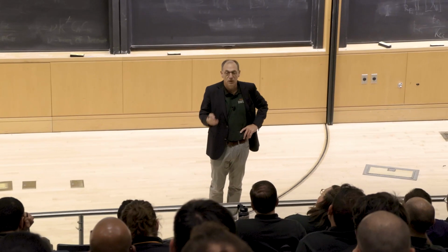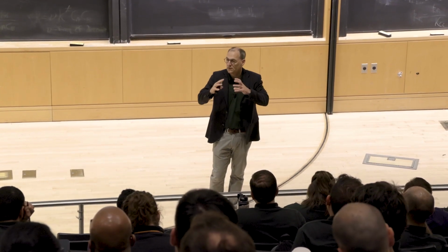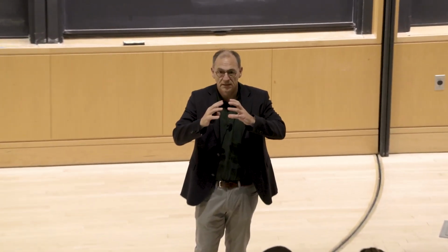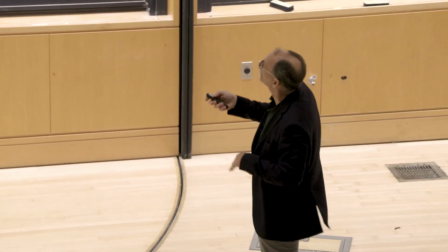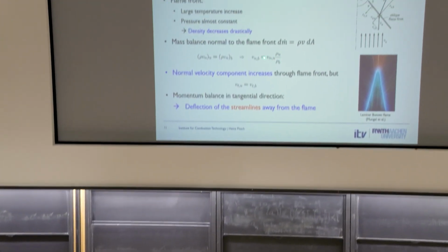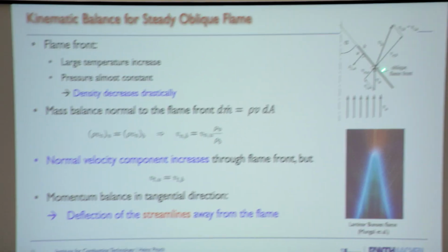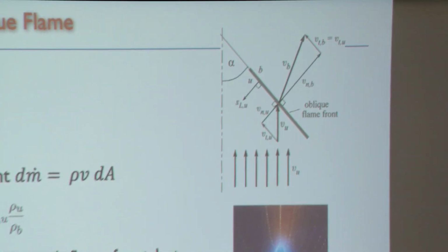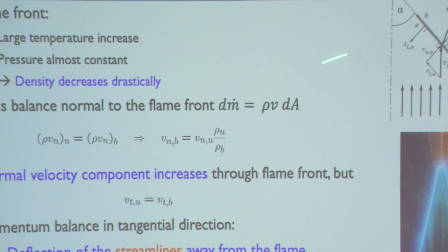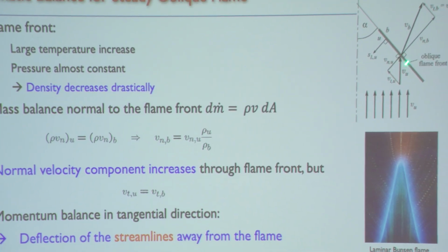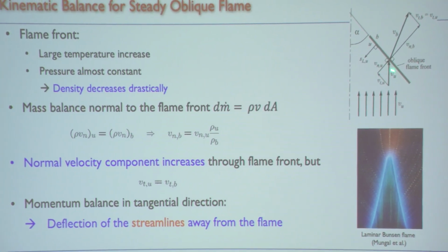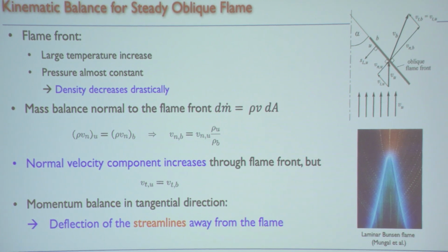That's why things explode, because you just increase the velocity, okay? Or, well, I guess if it's enclosed, you increase the pressure first. Yeah, maybe it's more the pressure, but anyways, you increase the velocity here, and that's interesting now because the normal velocity accelerates over the flame. The tangential velocity is the same, it doesn't do anything.